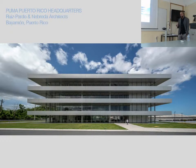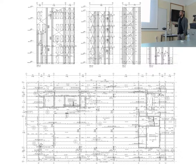So in this case we used coupled concrete shear walls as the main earthquake system. We had a really big core here, another core here. The building is regular in its geometry, but not in its stiffness. That is a really big issue. But the architecture was mandatory in this case, and we had to deal with these irregularities. We had this, and then we have some other shear walls at some other positions to try to deal with this. Okay.